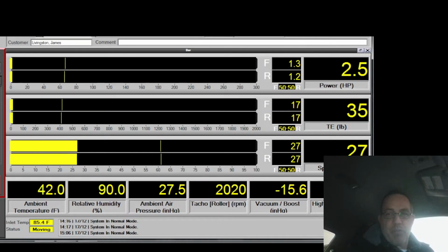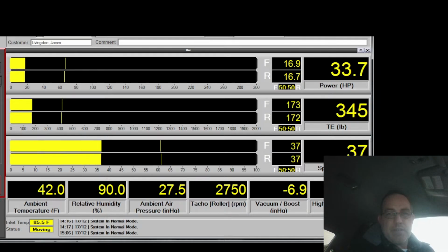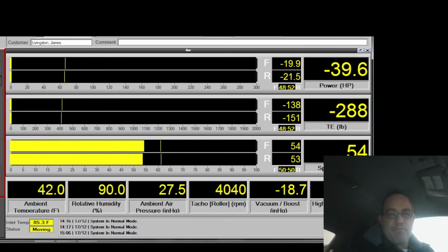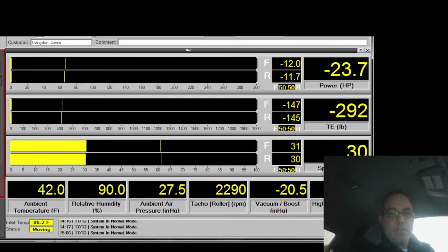And I already have done wall wetting adjustments. So I guess that means my SD, my volumetric efficiency table, is too high right there.